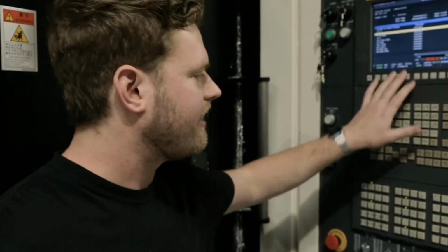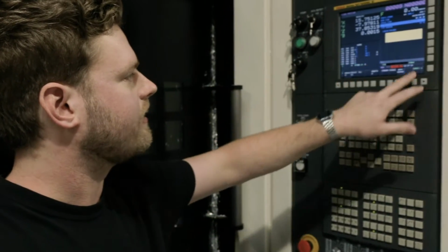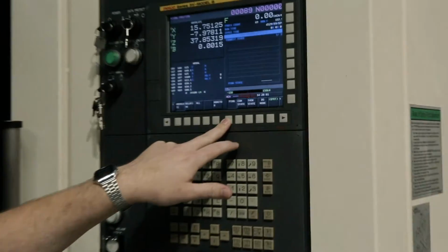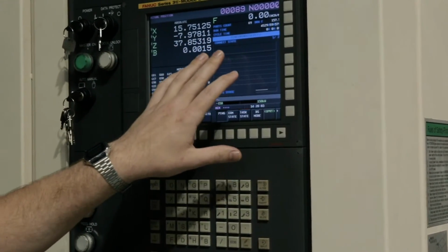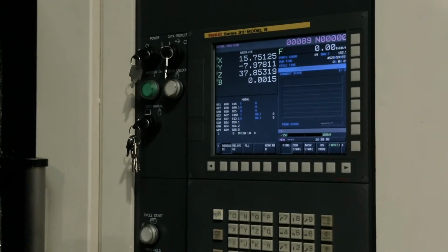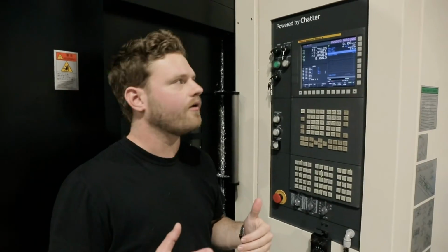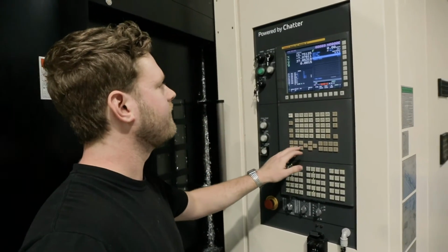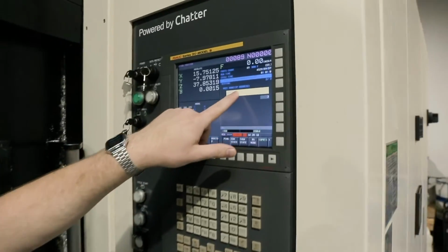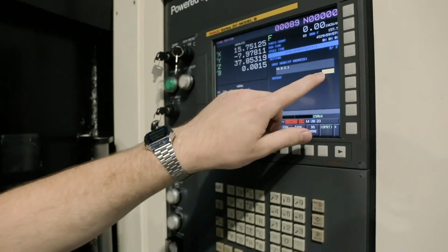Once you have that set up, if you need to troubleshoot, another thing you can do, going back into this screen that we were in earlier, is hit plus again and go over to the ping window. What the ping window allows us to do is try to communicate outward from the CNC machine to something else on the network. So we know where our router is on the network. We're going to hit page down, and this gives us a really simple interface. It's going to ask you for an IP address and a number of repeats.